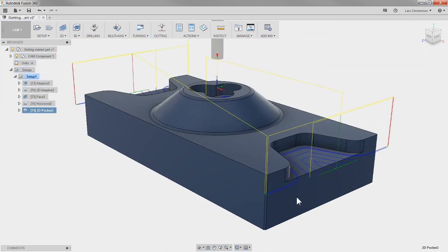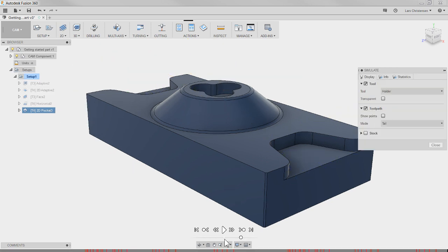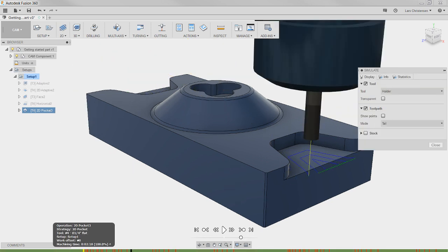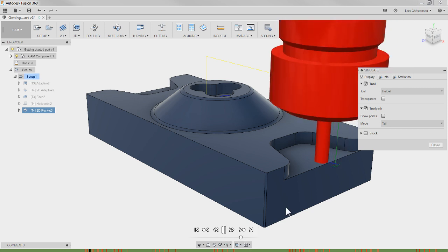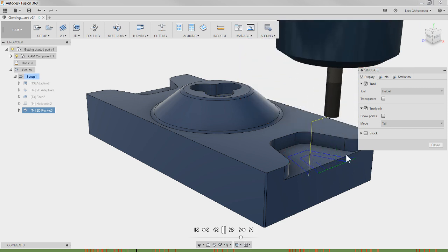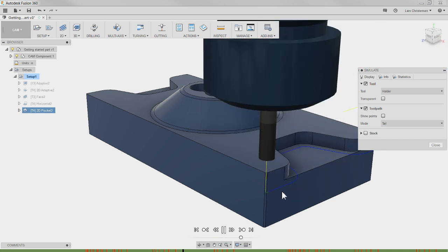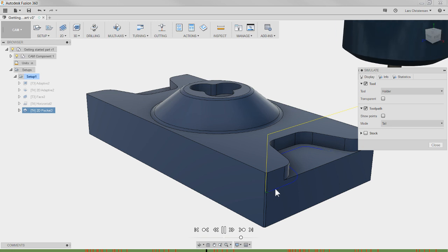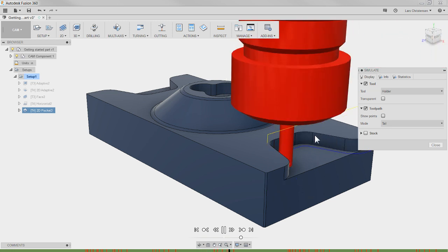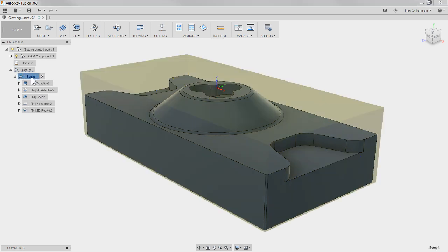What I think is fine in most cases, right, is just coming in and stepping in, and then in the end, just stepping in here. This is fine: machining the step over, and then in the end, just coming in here and removing that material. Actually, I just realized that the step over is not right. See, this is why you always gotta simulate.